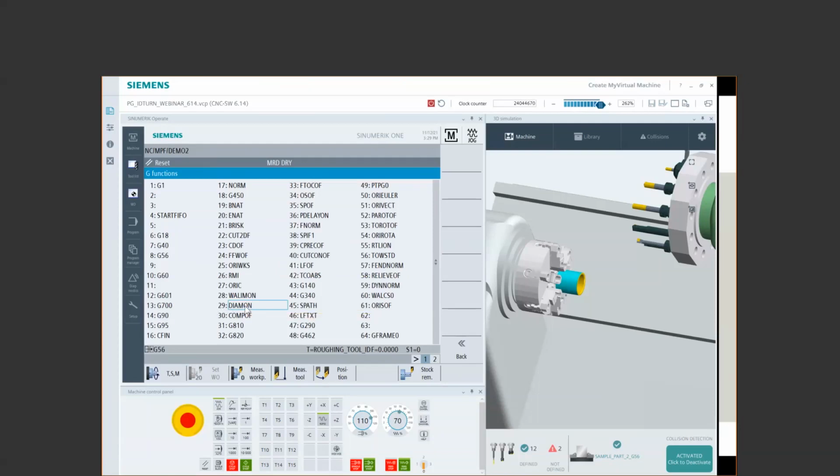But I still like to show you guys diameter mode off and diameter mode on, because if you have live tools, you will bounce between diameter mode off and diameter mode on. If you look at some of my other webinars where I got into live tooling, you'll see that I was doing that when I get into milling and drilling, specifically off center and centric drilling. On a simple machine like this, there's really no benefit to switching.